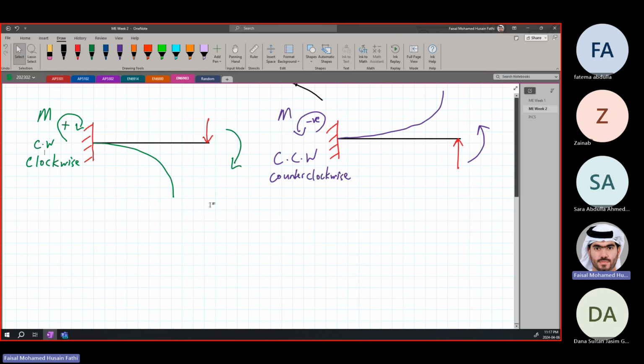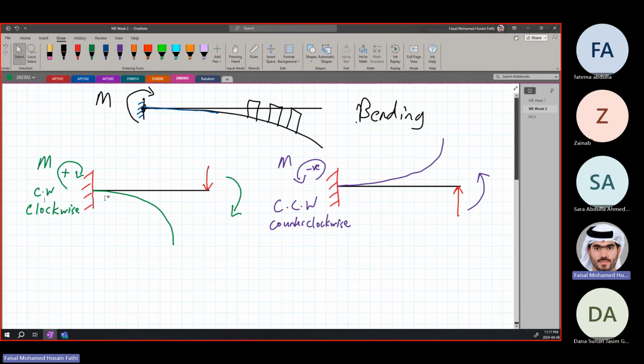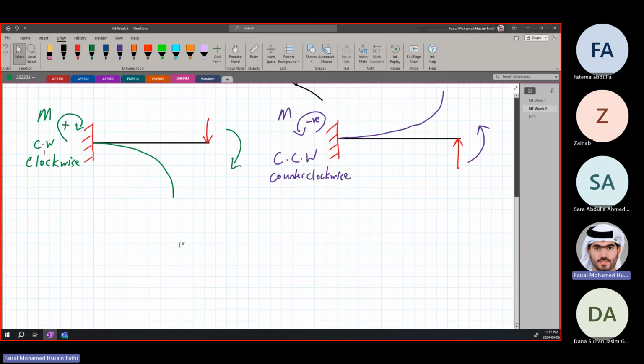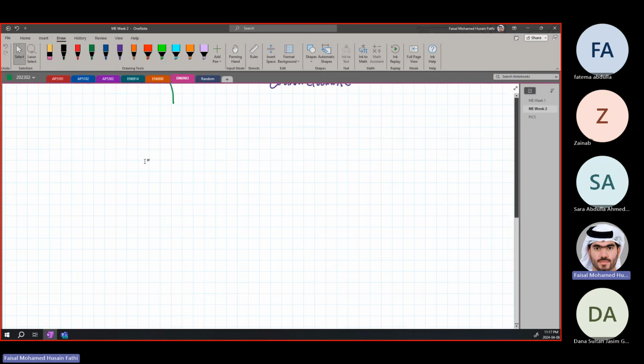So the whole concept of moment, as I said earlier, is to understand how much you need to counterbalance this force so that there is no movement. Now if you want to have a shelf, you don't want it to bend. You want it to stay flat. So you want to provide a counter to it somewhere here, and there is a force being applied here, so that no bending happens. There's enough support for it. That is the whole concept of moments, the principle of moments.